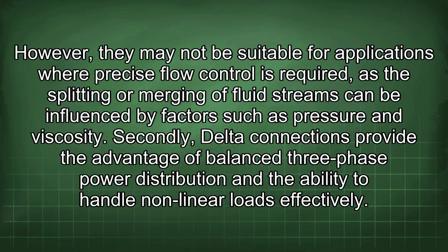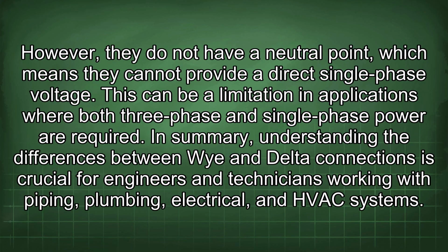Secondly, delta connections provide the advantage of balanced three-phase power distribution and the ability to handle nonlinear loads effectively. However, they do not have a neutral point, which means they cannot provide a direct single-phase voltage. This can be a limitation in applications where both three-phase and single-phase power are required.